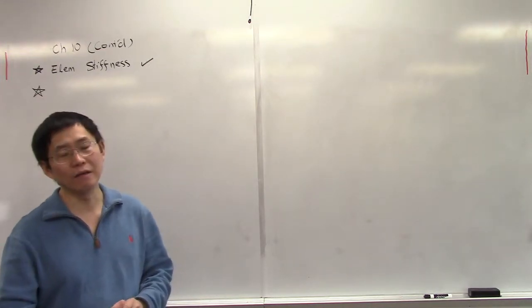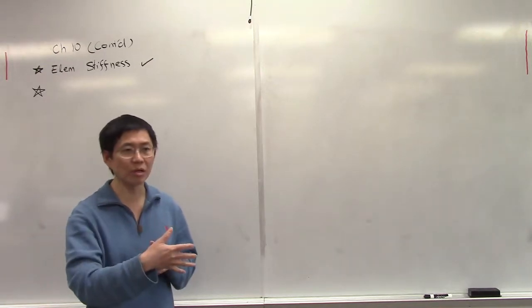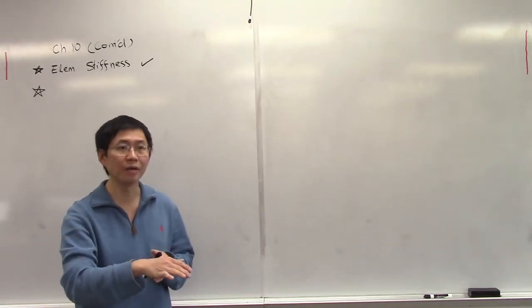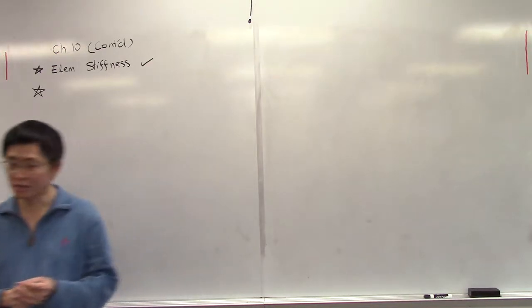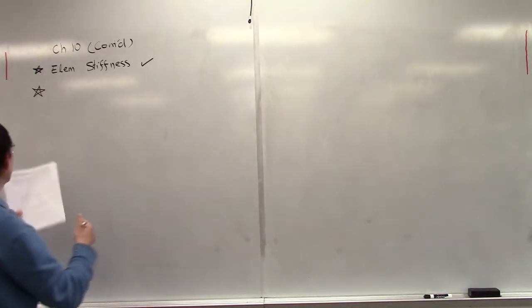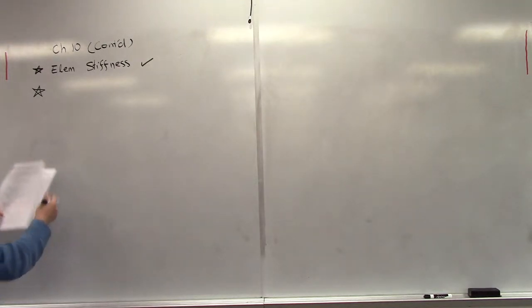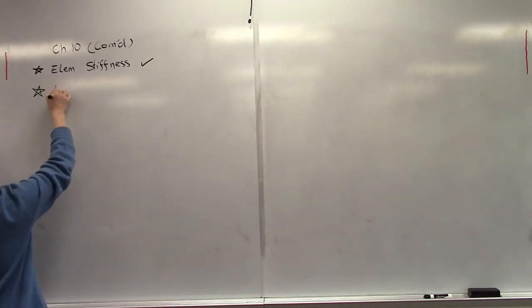And if there is applied traction but the essential boundary conditions are zero everywhere, just fixed, then the third term will also disappear. But when we talk about formulas, we will assume all those three things on the right-hand side may exist. Okay, so let's talk about the body forces.